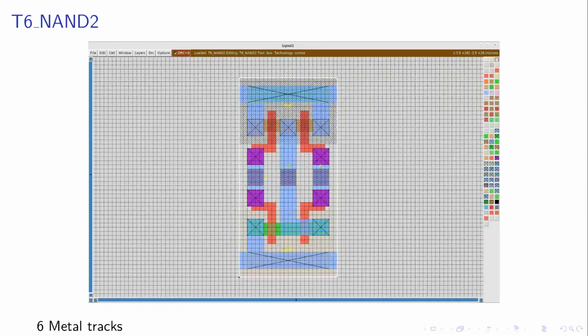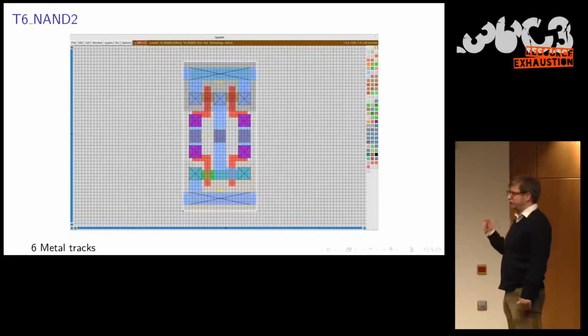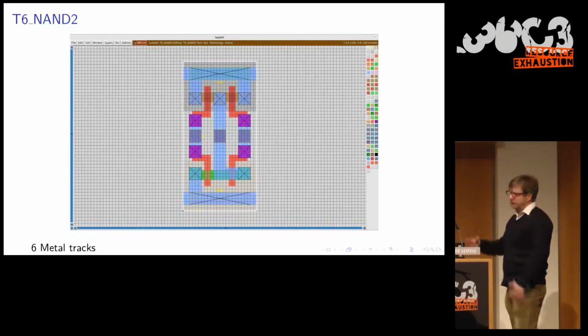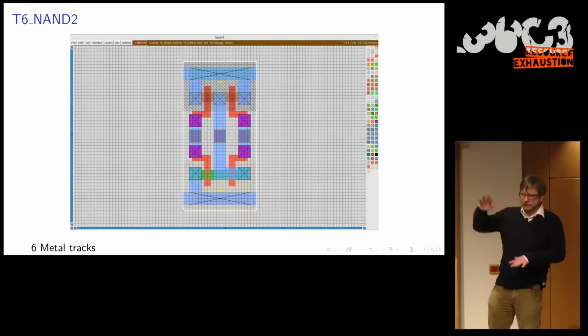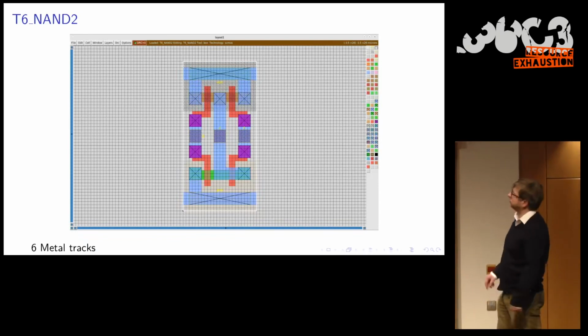So we see in the MOSIS rules this has a size of 4 lambda. And the MOSIS rules also define the difference to the next metal. So we have 4. This gives a grid of 8 lambda. And this grid is also used when routing amongst different cells. And that's what is called tracks.